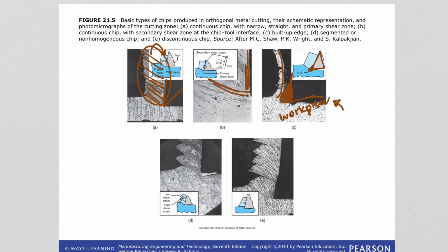So the tendency to form build-up edge can be reduced if we increase the cutting speed, decrease the depth of cut, use a sharper tool, use an effective cutting fluid. So there are factors that can be used to reduce the formation of the build-up edge.